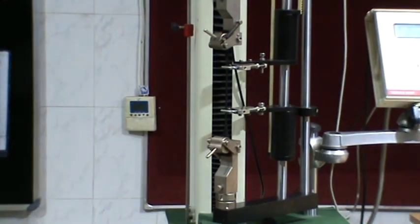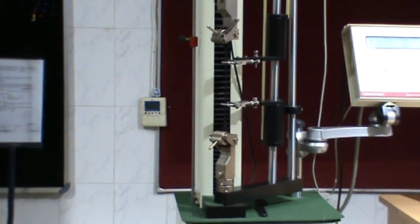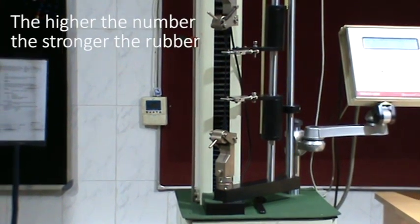D. Tensile strength. The strength of a rubber compound is measured in megapascals, MPa. It is the force in newtons being applied when the rubber snaps, divided by the cross-sectional area to give the tensile strength. The higher the number, the stronger the rubber.